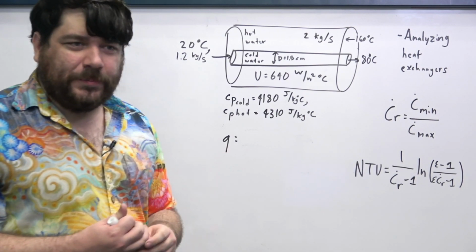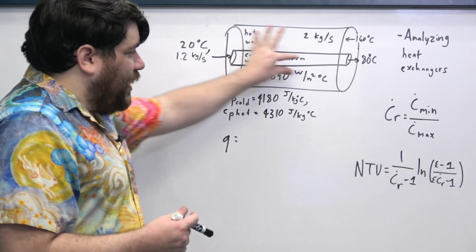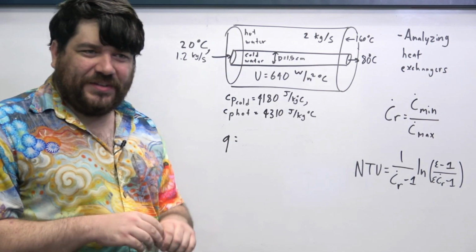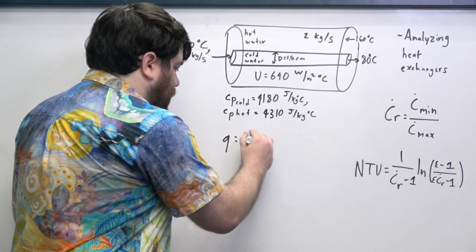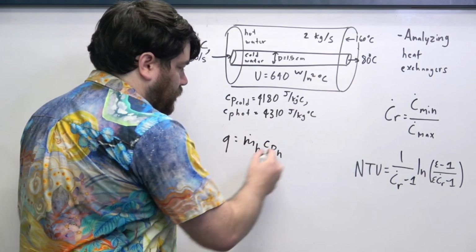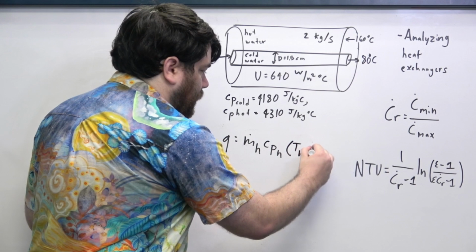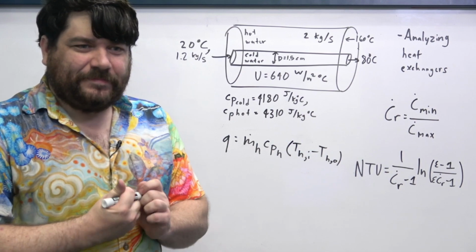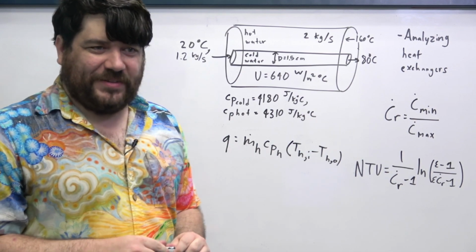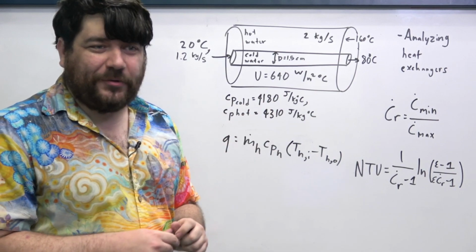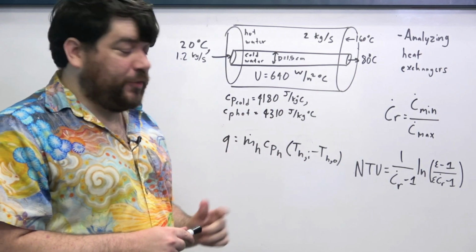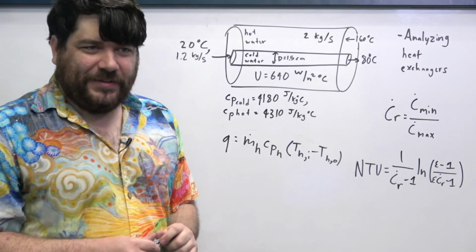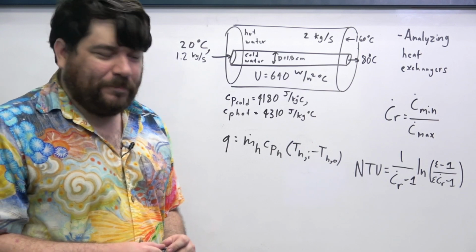And so we can find that the Q that is arriving into the cold liquid from the hot liquid is the same, of course, as the Q that leaves the hot liquid. And so we can now write this down in the following form. And because we know these mass flow rates and specific heat capacities for both of the liquids, we know this inlet temperature, and we found the Q from our previous calculation, we can therefore find the outlet hot temperature, T_H,o.